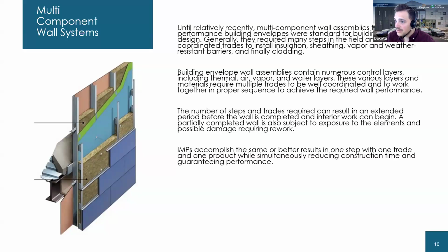And as far as competition with IMPs, unfortunately, there are a few flaws we have to recognize that become apparent when we start analyzing these with a microscope, right? IMPs can be mounted directly to studs and work in every single climate zone, pretty often with long spans using steel systems, not having to rely on many fasteners, and not having thermal bridging to be concerned with. Multi-component systems, by contrast, unfortunately have a few built-in Achilles heels.